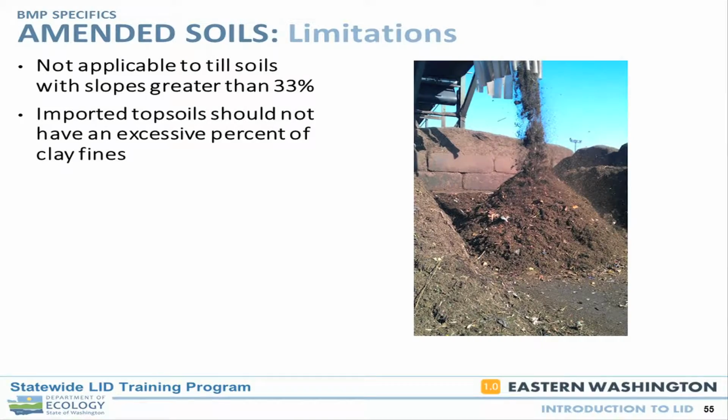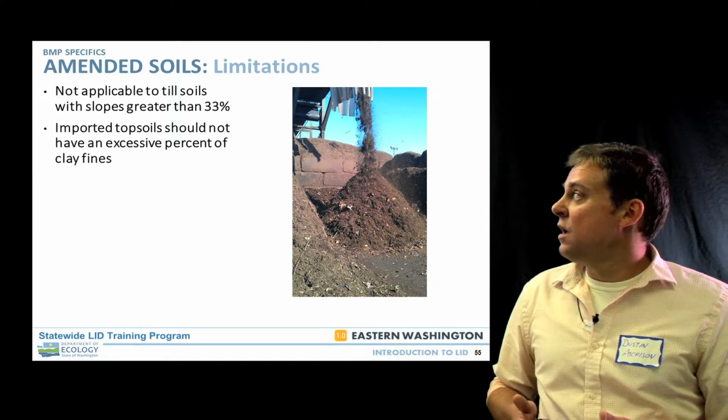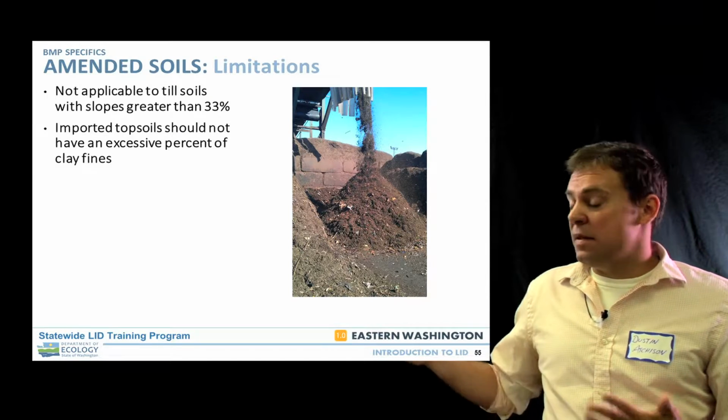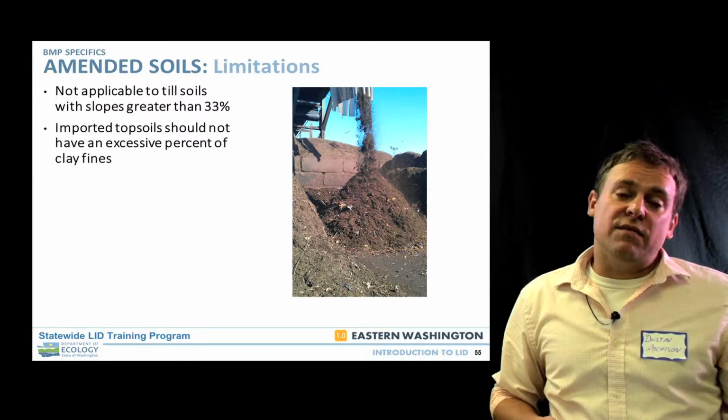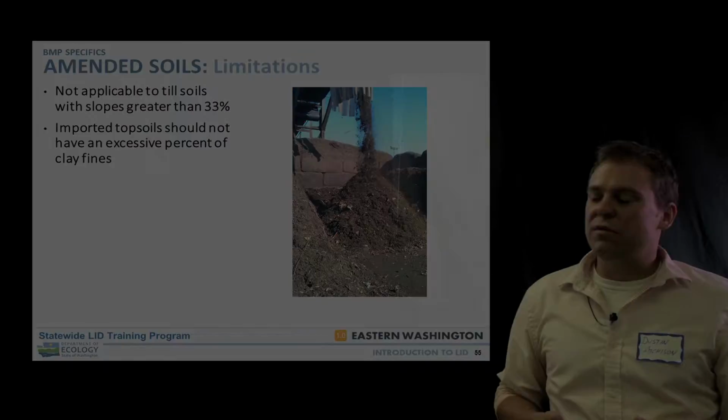Limitations of where you can't use this practice: steep slopes. Don't go and disturb them and go till them up if they're greater than 33%. That's going to create an erosion and perhaps a stability hazard. Imported topsoils themselves should not have excessive fines or clays within them because otherwise they're not going to provide that function that we're shooting for.